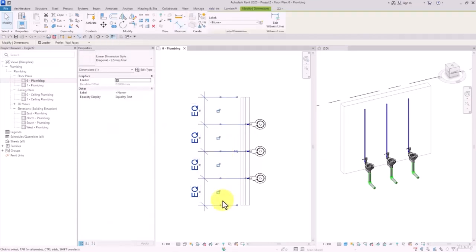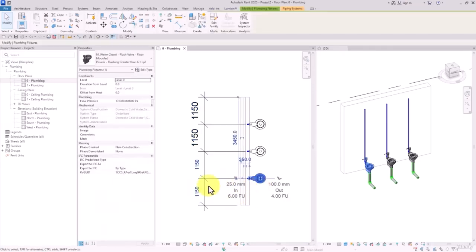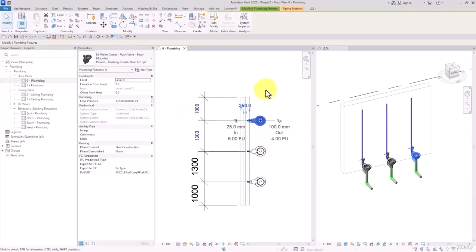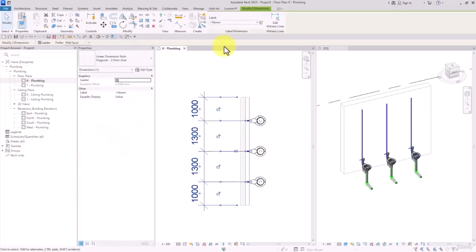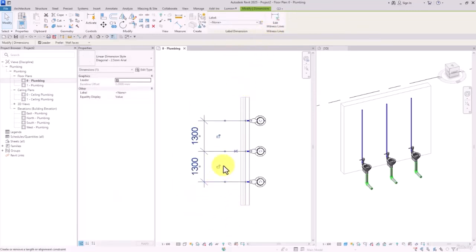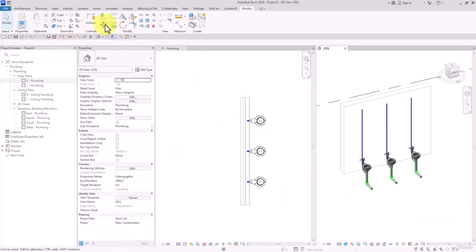And if we didn't like the distance that we've got, we can always go ahead and modify it. For example, I'm going to set this one on 1 meter. Then up here again, another 1 meter. Now I'm going to select this line, then remove this, and do the same down here. Now it'll be equalized based on this midpoint. Alright, and now we can remove these. So this is how we can use items such as move, copy, and so on.